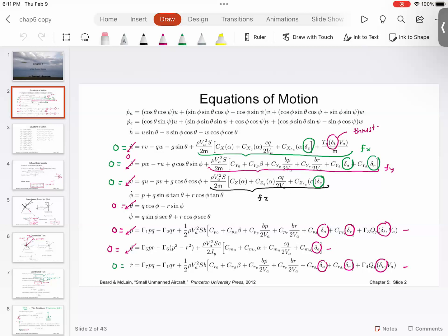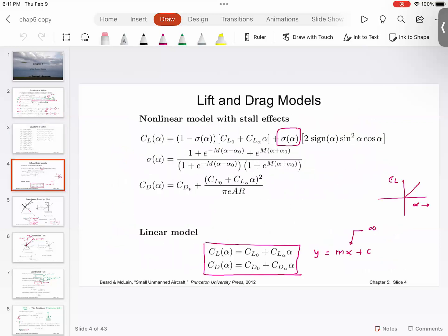So the thing here is to identify the states that absolutely have to be zero, and identify the states where there has to be an absolute constraint. Once you do that, these equations become super complex. And once you start coding it, you will realize that they actually include the effect of control surfaces. So depending upon the exotic control surfaces that you have, you will have different terms.